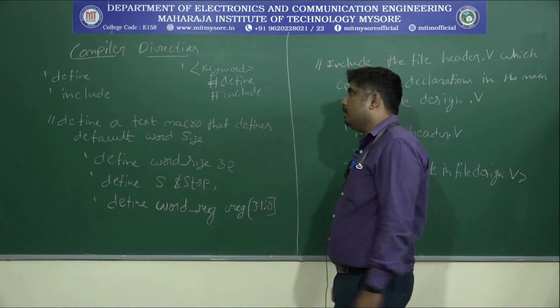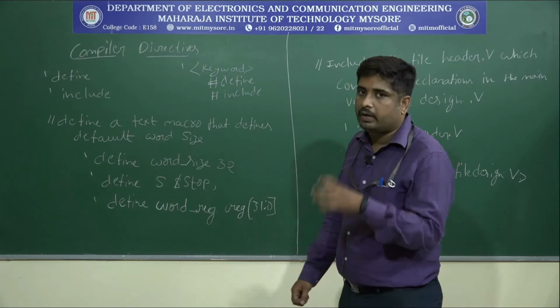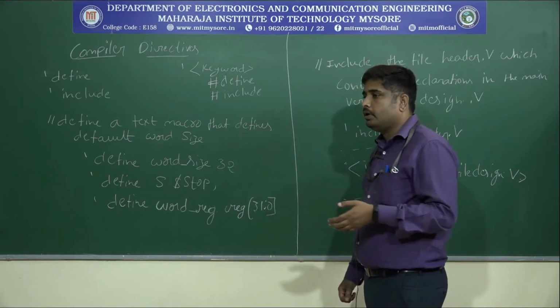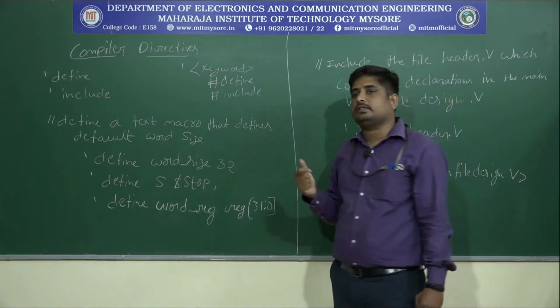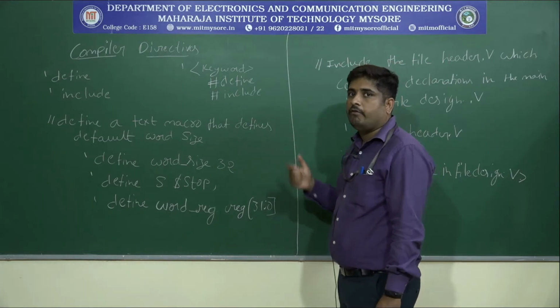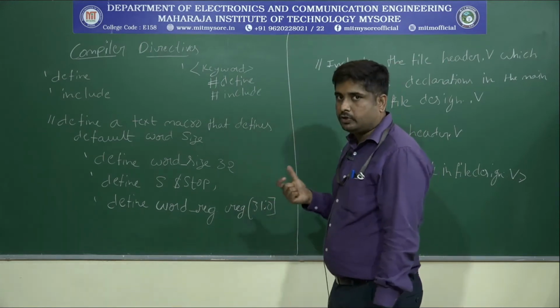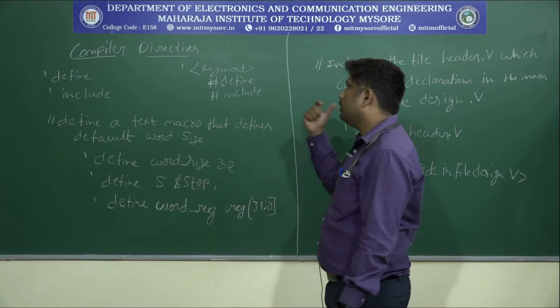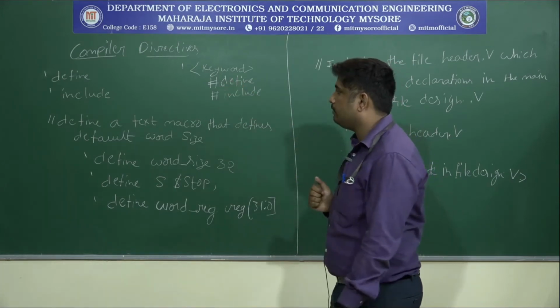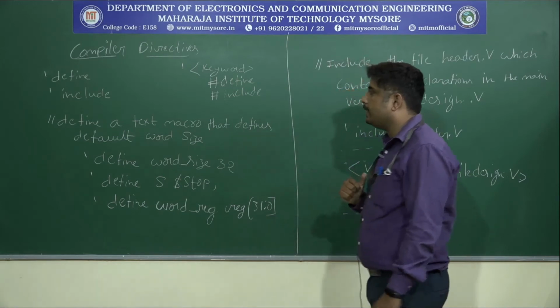It's used to define a particular text in Verilog HDL. When you consider it, the compiler substitutes the text of the macro wherever it is needed. So wherever you need the text, at that time we have to consider a tick define. Let us take an example here.